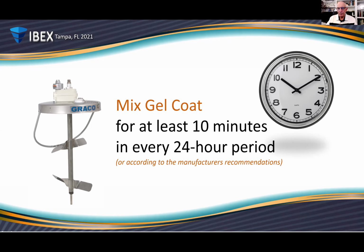Now, in mixing gel coat, the rule of thumb is mix for at least 10 minutes. This is operating under the assumption that you have an appropriate mixing device that can turn the drum from the top to the bottom. So you've circulated the entire drum of material or 5-gallon pail of material within those 10 minutes. So mix it for at least 10 minutes within every 24-hour period. So if I mix gel coat right now, I can spray it tomorrow morning.